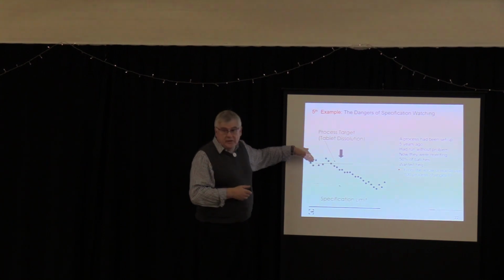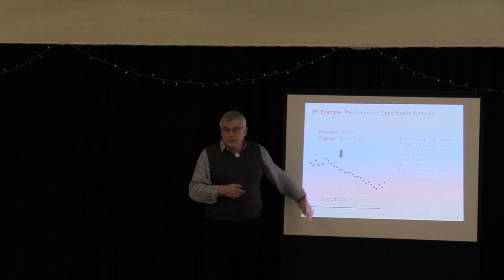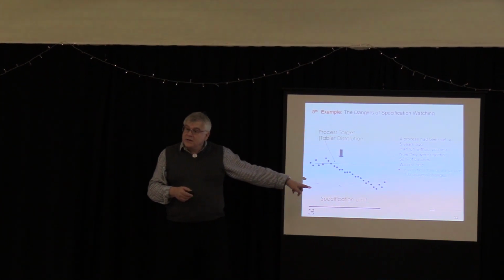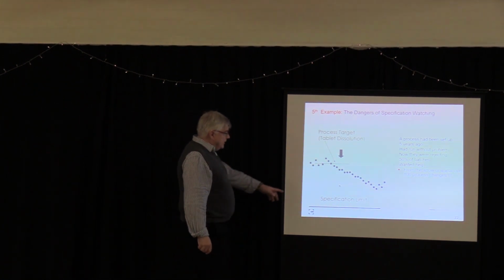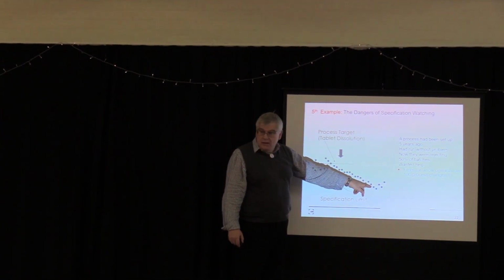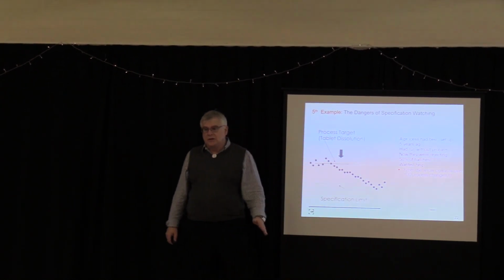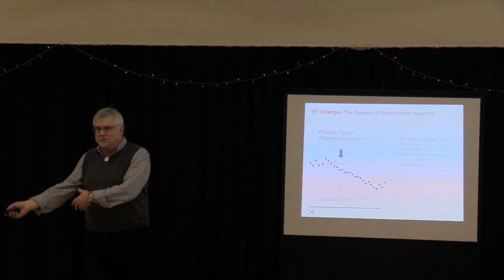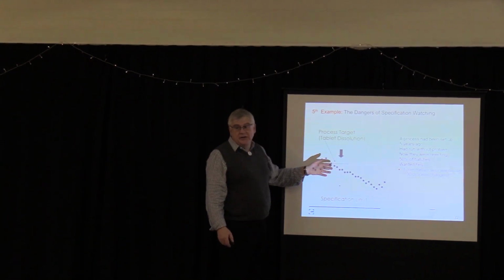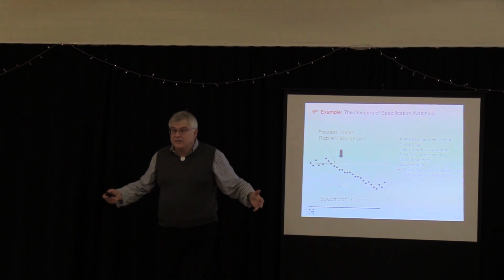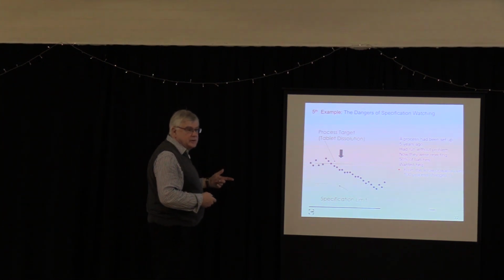So to start with, everything was okay, and then about 1 year in, things started to drift. But they were still above the specification limit, so everything's okay, isn't it? Until, of course, they hit here, when the actual level is around about the specification limit, and so 50% of the time they pass and 50% of the time they don't. But in the intervening time, they never did anything. Well, yes, they did. They changed the production process, and that's why they started to drift.